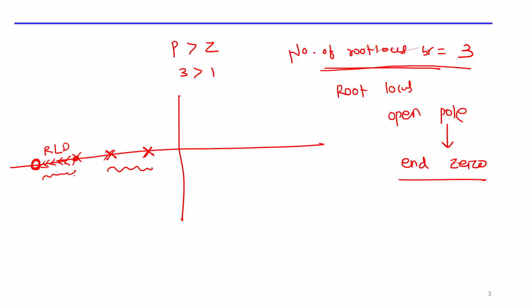I am saying that whenever a pole meets a zero, the root locus diagram is complete. So one pole, let's say, meets a zero, so one root locus branch is complete. But there are another two poles, and there is no zero left. Then how will they meet? At which point will they meet? They will meet at the breakpoints, breakaway, and from there they will go to infinity. Yes, that's the answer.